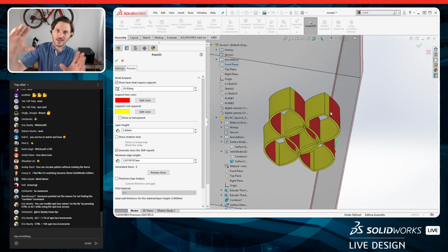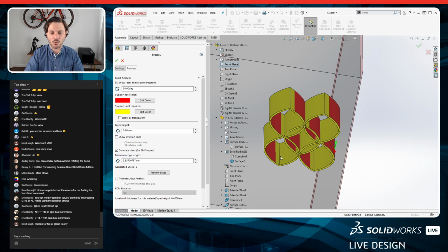I'm kind of at an off angle here because I have my rotate about seam floor. But this will give me an idea about where I want my support material to go. And I can even change this value that is basically intrinsic to most printers that said, well, if you have an overhang region that's more than 30 degrees, you're going to need support. Less than that, we can handle it. It's a pretty nice little tool here.